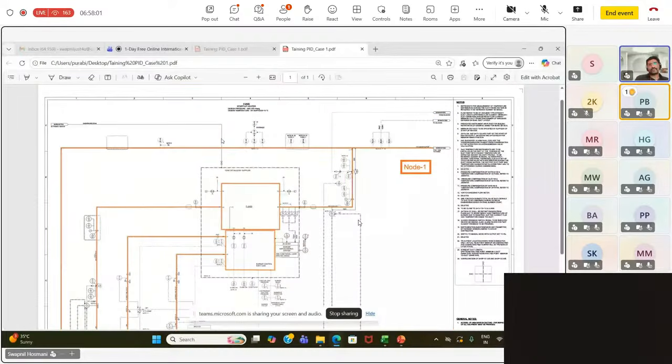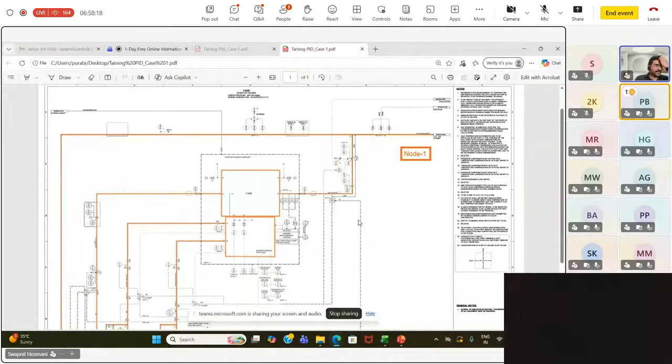I have confined this only to this P&ID, so that downstream is a pretreatment reactor or carbon capture reactor, and this is a preheater whereby you heat the flue gas to the prerequisite temperature required for the reactor, and that is done through two sources of fuel.